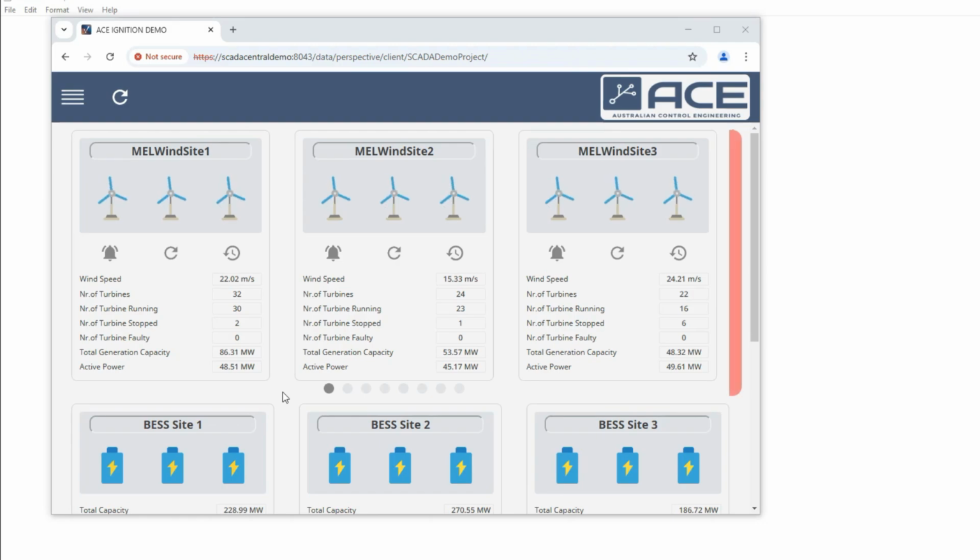This is achieved through a UNS-based comparison between the central gateway's site OPC tags and those currently read as part of the OPC translation of MQTT topics received from the sites to the central gateway's broker, where if new data is received based on the UNS, whether it be asset or entire site, and discovered during browsing, templated HMI displays will be formed using this data, alongside any current disparities corrected.